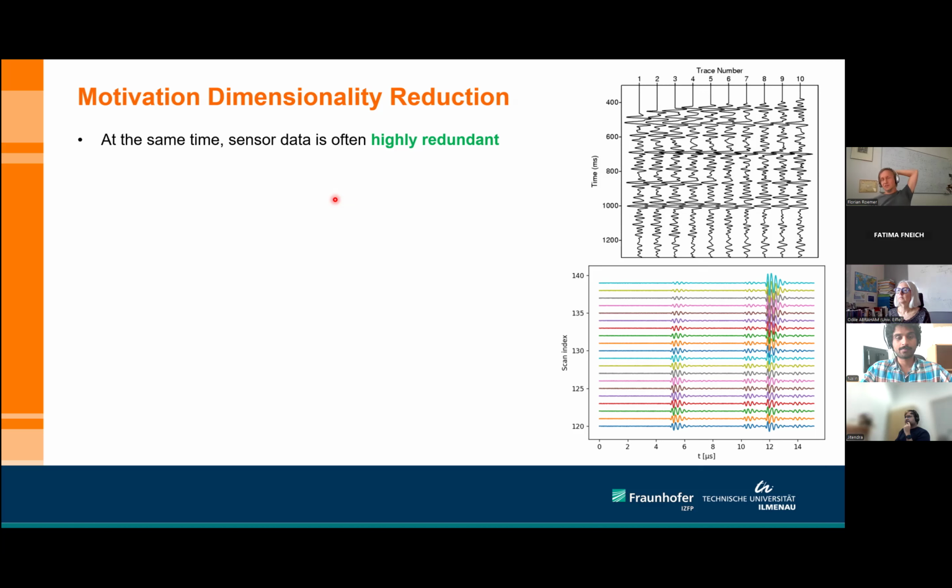If you make a dense ultrasonic scan, what we're actually sampling is the wavefront of an acoustic signal. And the wavefront, for physical reasons, cannot change really abruptly. There's continuity conditions, especially if you are on a continuous surface. So there must be an amount of correlation. Of course, it depends on what kind of wave phenomenon and how finely you are sampling, but the gist of it is there must be. So it's not surprising adjacent channels are similar.